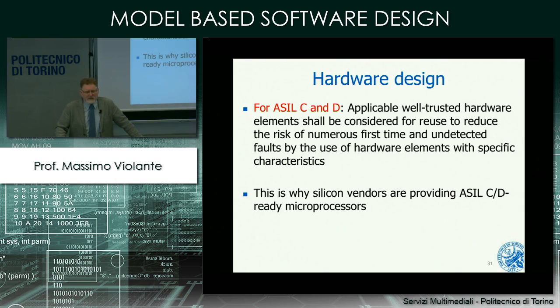Conversely, if we have an ASIL-C or ASIL-D application and we have sensors there, probably duplicating the sensor is very important, because we must be sure that either we are able to always sense the correct information, or we are able to understand that the sensor is not working properly with the shortest fault reaction time possible. Okay, these are the types of reasoning that you have to put at work when addressing hardware design with ISO 26262. We will do some exercises to better catch this concept.